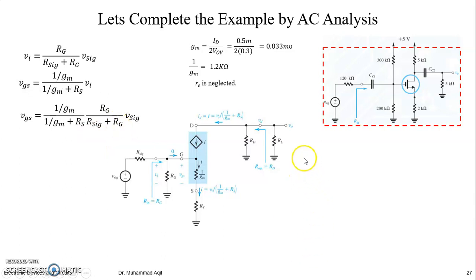And then we can write the equation of the output. The output voltage is current multiplied by the resistance. The resistances are only these two, the parallel combination of these two, having a current, which is this I, or we can say gm VGS. So current times these resistances will be the voltage across these at this terminal, but with a minus sign because this is the current leaving the terminal for these resistances. So V out is minus gm VGS times the overall resistance value.